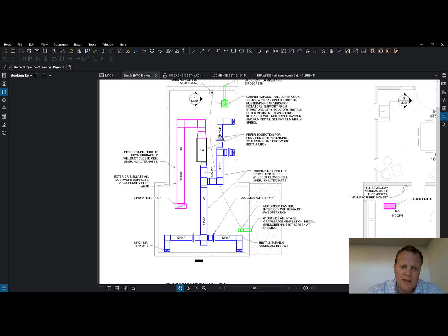And then by the time it hits this ductwork, it's now 12 inches wide, 4 inches tall. Why did it keep going down in size? Well, it lost volume of air. It didn't need to be that big anymore, right? So the air comes this way, and because it was so large here, some of the air is going this way and some of the air is going that way, and they want to reduce the size of the ductwork so they don't lose the speed in the air. And it's wasteful too.